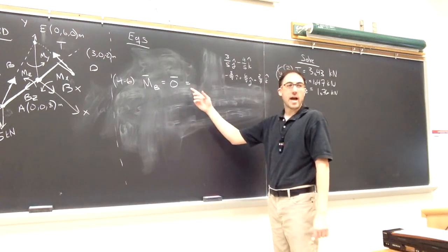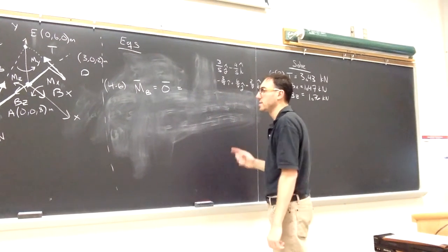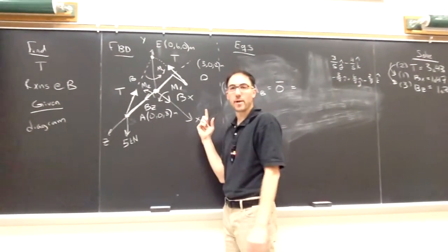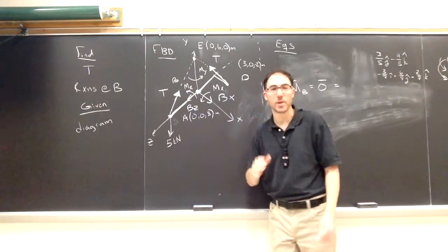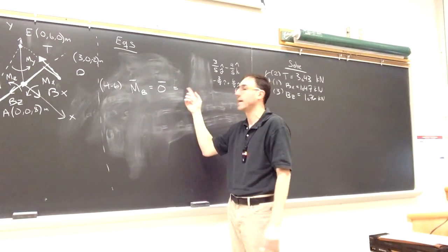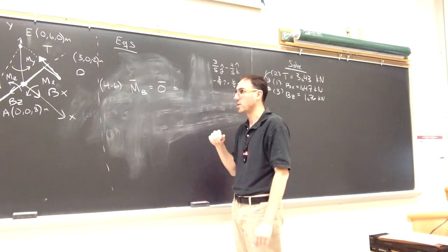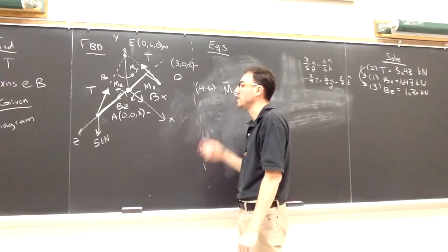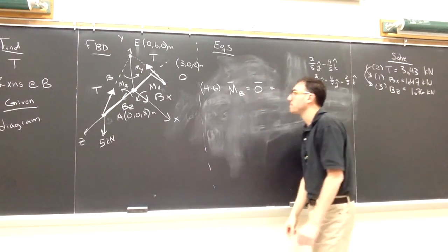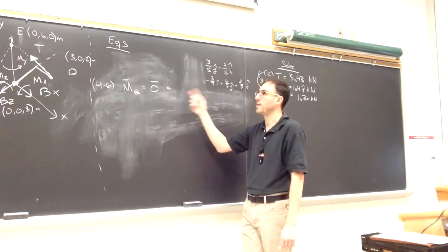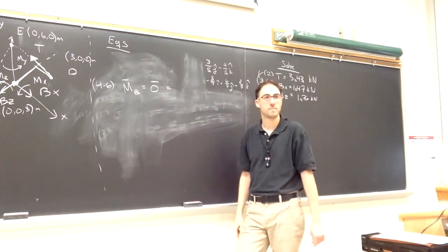All right, so we need to account for all of the things that cause a moment around point B. In 3D, I suggest actually starting with couples first and then moving to forces. It's very easy to forget to include couples in this equation, I find otherwise. So we want to find first, what are the moments caused by couples? So what should the right-hand side start to look like? What couples create a moment around point B?